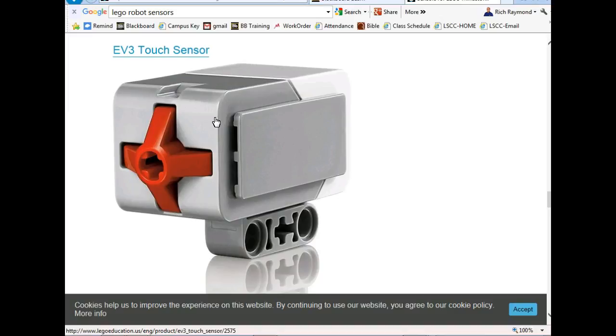And we can go look at the manufacturing line. It's a lot better to see them. These guys got limit switches all over. And basically in that situation, that's exactly what they're doing. They're giving us the limit of travel that something can go to. But I've seen them used as counters. I've seen them used as all kinds of stuff. Presence detectors, you know, why turn something on if nothing's there? Right.